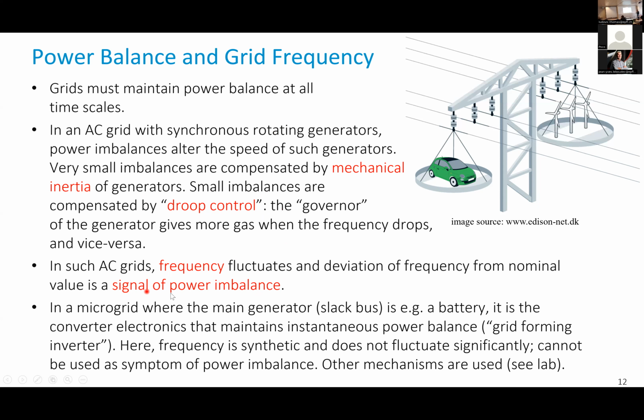The first thing also to remember is that the deviation of frequency from its nominal value is an implicit signal of power imbalance. This is why, in technical papers or technical user guides, this is often called frequency support. We're supporting the frequency. We're helping the frequency get to its nominal value.